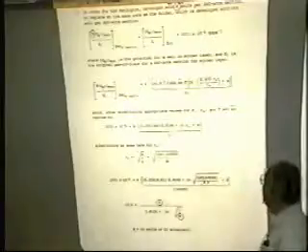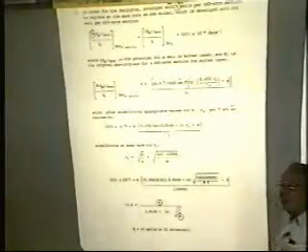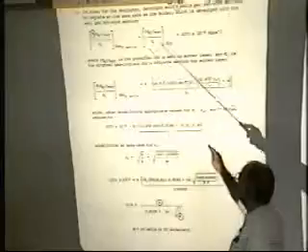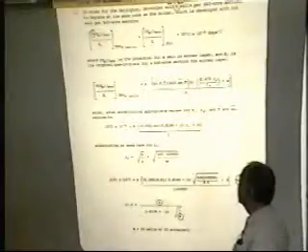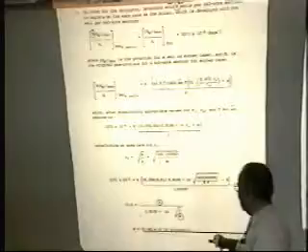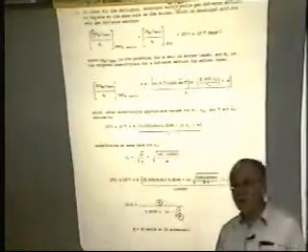If I want to make the Harrington and the Kreider deplete at the same pressure at the same time, I know that the ratio of these has to be equal. So I determine what it is for the Kreider, and I try and determine how many wells do I have to drill in order to make these two equal. And you go down through the calculations, it turns out you'd have to drill 29 wells, or have a 20-acre spacing, for the other two layers to equally deplete.